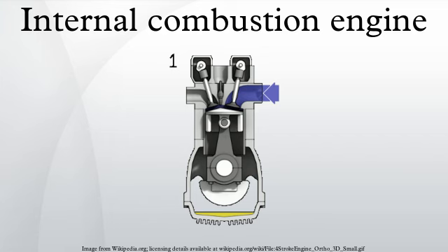Small displacement, crankcase scavenged two-stroke engines have been less fuel efficient than other types of engines when the fuel is mixed with the air prior to scavenging, allowing some of it to escape out of the exhaust port. Modern designs use air-assisted fuel injection, which avoids this loss and provides more efficiency than comparably sized four-stroke engines. Fuel injection is essential for a modern two-stroke engine for it to meet stringent emission standards. The problem of total loss oil consumption, however, remains a cause of high hydrocarbon emissions.